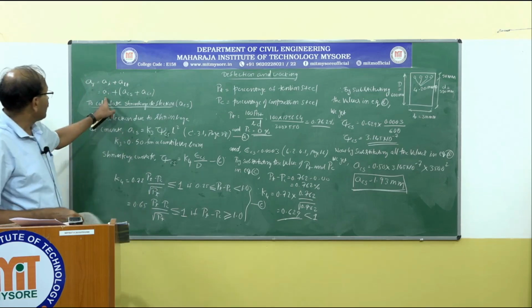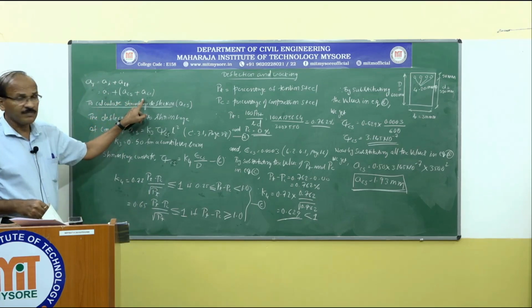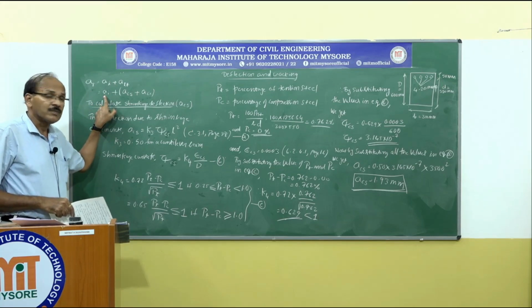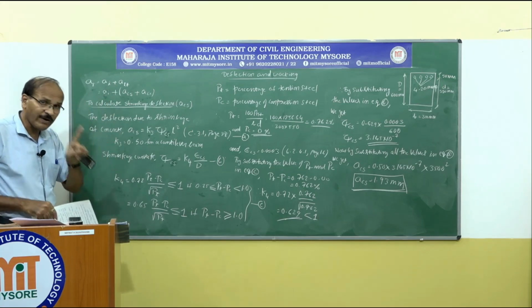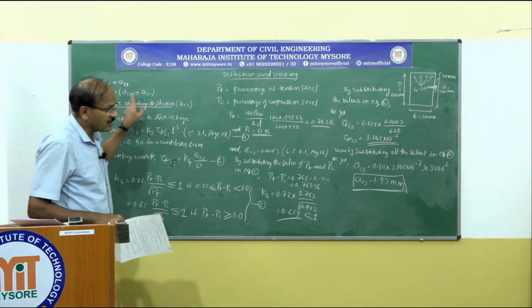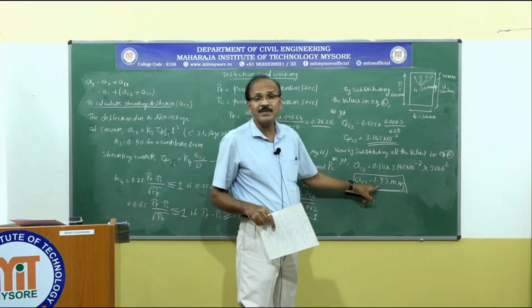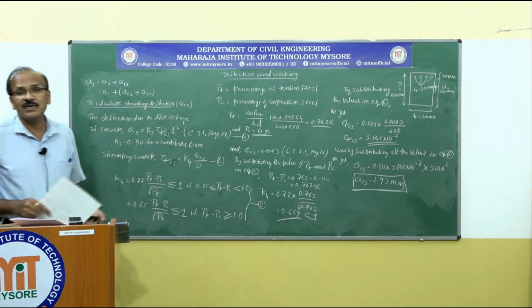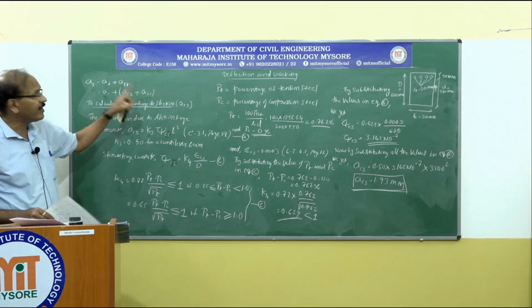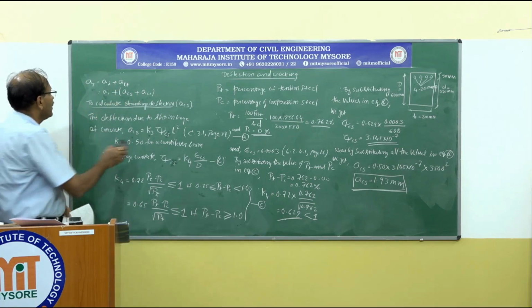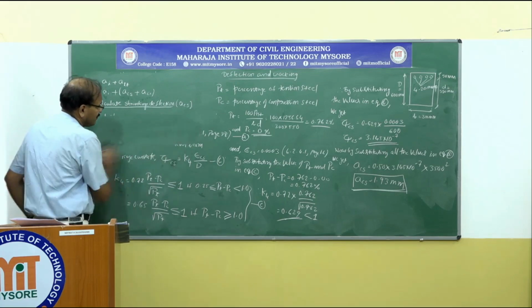So if you come back to this equation, we calculated this. This was 7.45 millimeter according to our calculation. We calculated this just now, which is 1.93 millimeter. The next step is we need to calculate ACC, that is the deflection due to creep of concrete. Next, let us find out that.